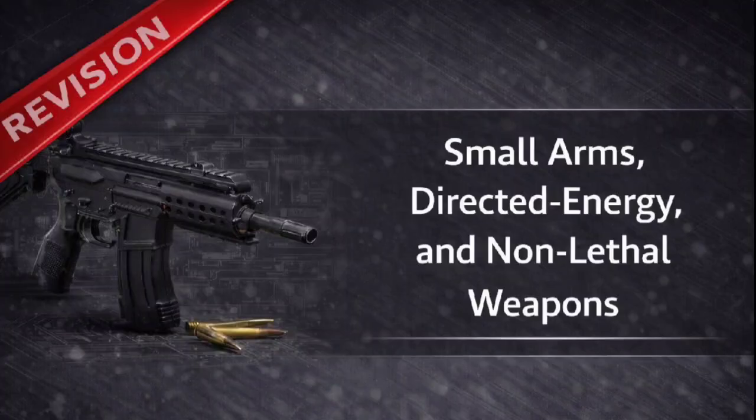Which is why short recoil seems to dominate modern designs. It absolutely does. In short recoil, the breech remains locked only for a short, controlled travel distance, just while the pressure is highest. Once that pressure drops, they separate immediately. And the benefit of that? This minimal movement permits a high rate of fire, and it's significantly more accurate than the long recoil design because the moving mass and the barrel disturbance are minimized.